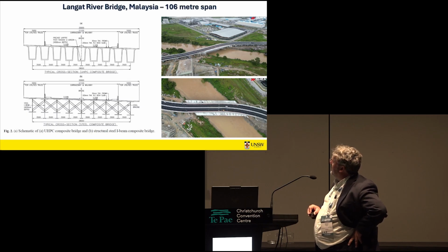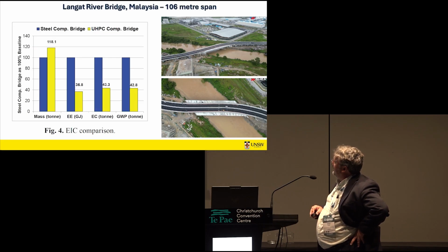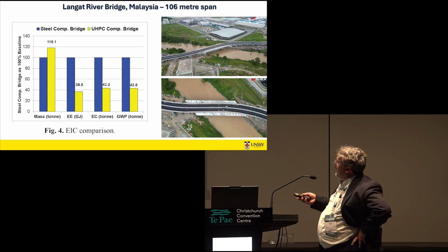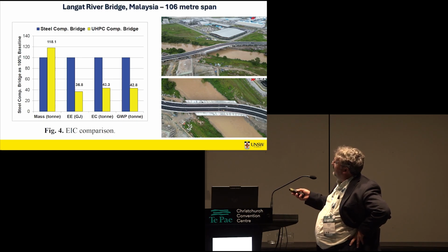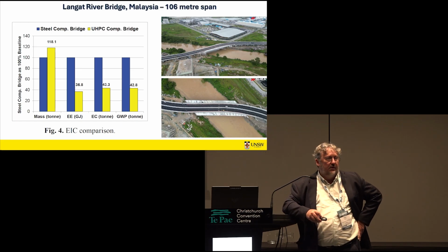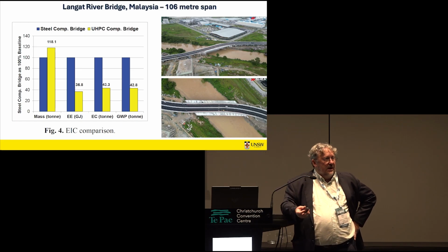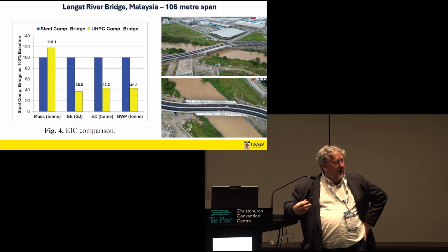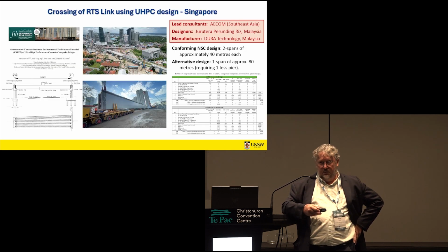UHPC bridge to date. And if we look at this particular bridge, those examples, we see even though the bridge itself weighs about 18% more, in terms of carbon efficiencies, it's less than a half. Right? So we've taken out a higher carbon solution and replaced it with a lower carbon one.